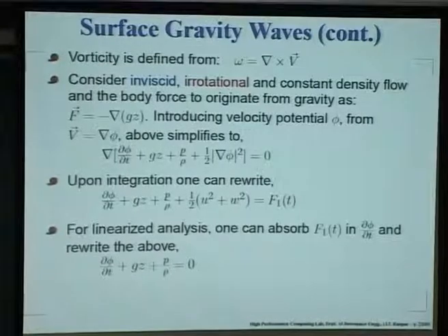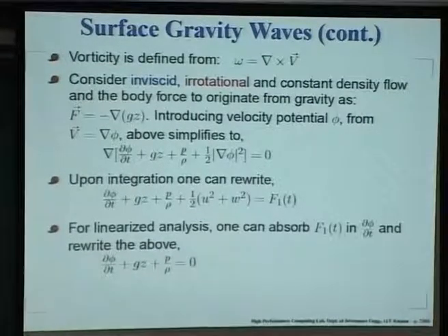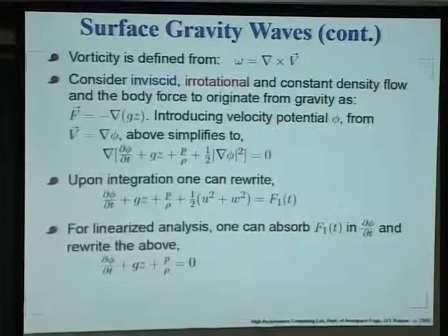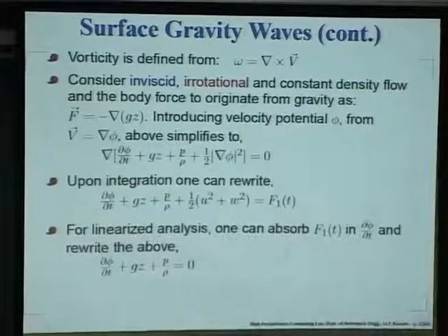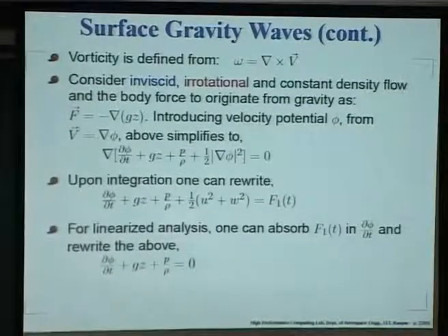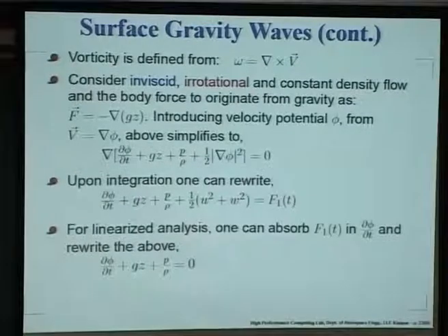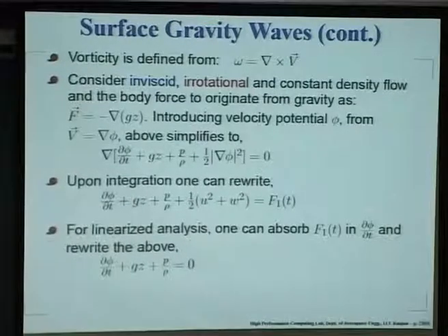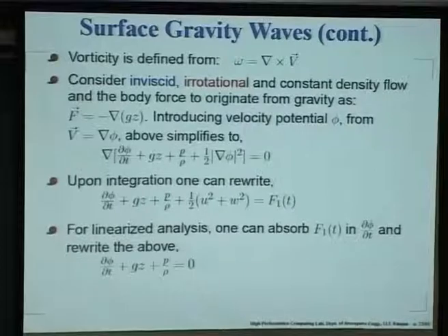So, you can integrate, and this is what you get. This is the general form of Bernoulli's equation that you may have done if you have taken any course on fluid mechanics before. This is a little more general because we are talking about the unsteadiness of the flow as well.